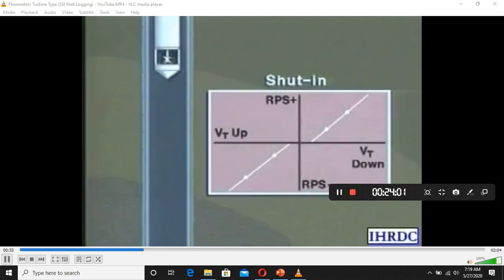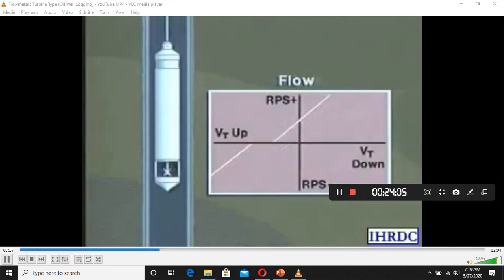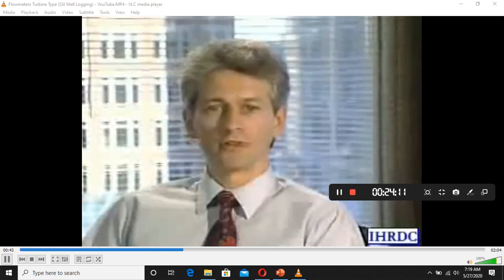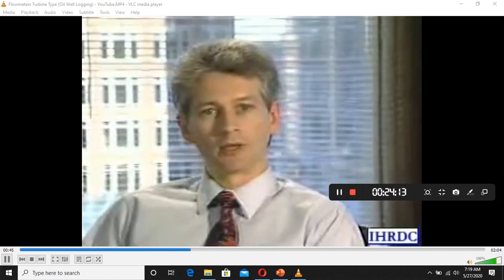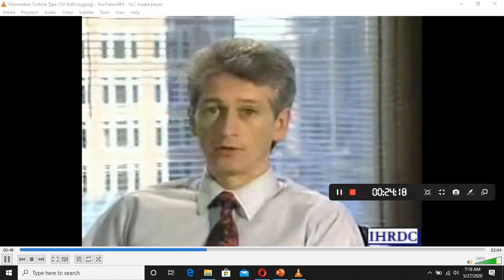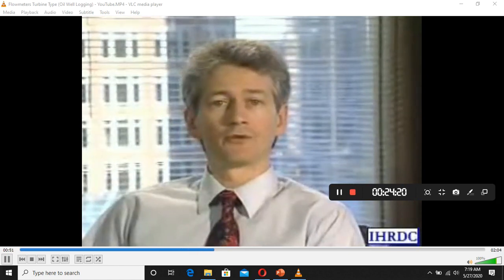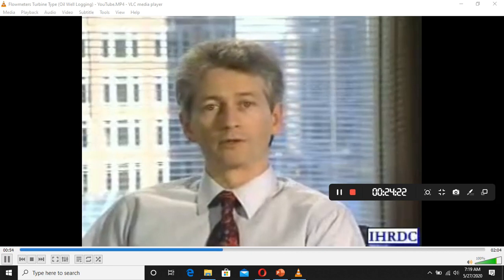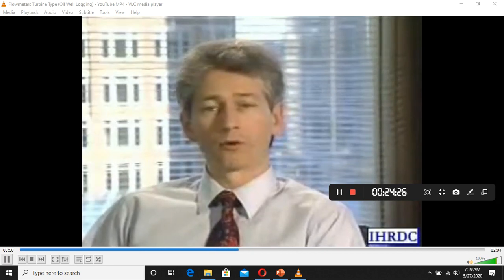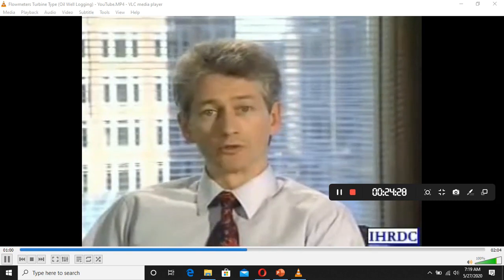When the spinner encounters an upflow, as would be expected in a producing well, the effect is to shift the response curve of the tool to the left by an amount equal to the upflow velocity. The flow velocities measured are those seen by the spinner turbine blades. If the spinner is centralized, and it should be for best results, it has sampled the flow from the center of the wellbore, which is too high and not representative. As a result, a flow profile correction factor must be used, typically 0.83.